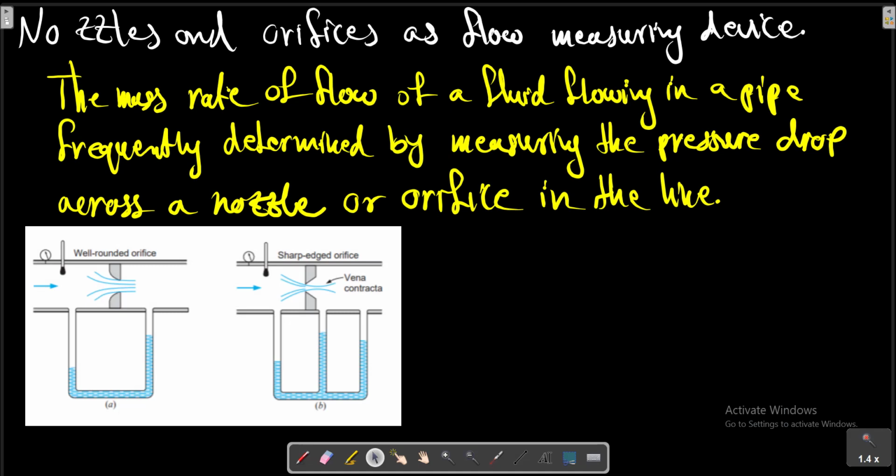The ideal process for such a nozzle or orifice is assumed to be isentropic flow through a nozzle that has a measured pressure drop from inlet to exit at a minimum cross-sectional area equal to the minimum area of the nozzle or orifice. The actual flow is related to the ideal flow by the coefficient of discharge, which is defined in the previous section. The pressure difference measured across an orifice depends on the location of the pressure taps, as indicated in the picture.